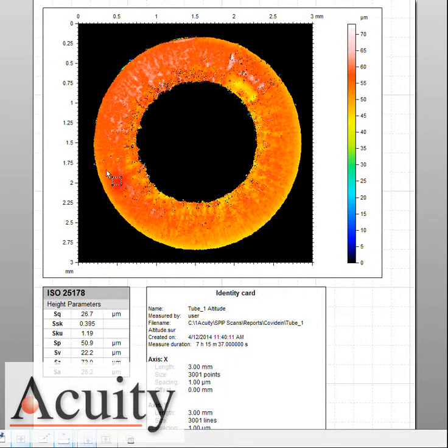So to recap, the white light confocal can make this measurement very easily. It is a lot of data, so if we did need to go faster, then we'd probably want to consider using our multi-point line sensor, which has 108 points across there. So we could collect over 324,000 points a second, and would be able to scan this 100 times faster and get that information out if needed.